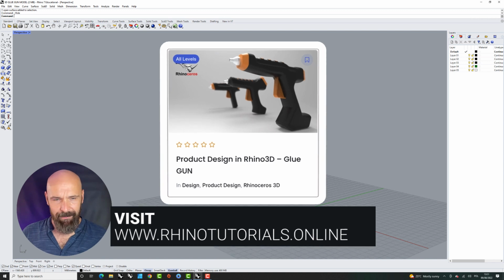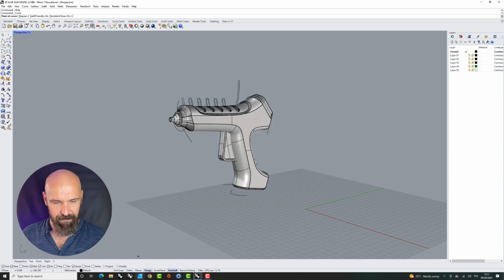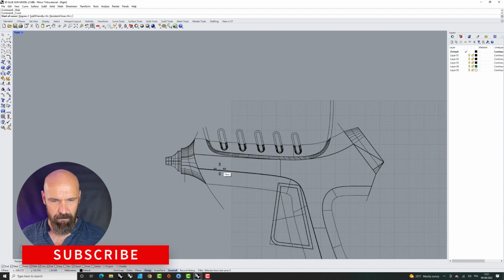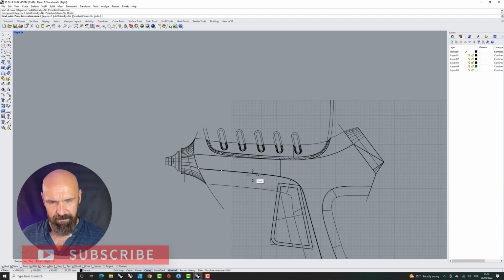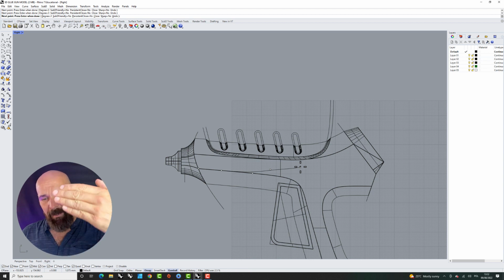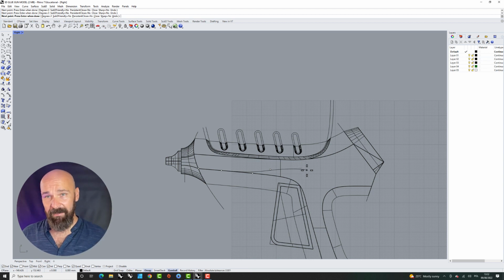If you're drawing a curve, especially without planar on, and you, let's say, start on that edge from the right view here, and you keep going on top of that edge, and then you decide to change the direction, and you click just on the default plane like so, then your line is going to be on a default plane behind the object, so it messes up the curve.